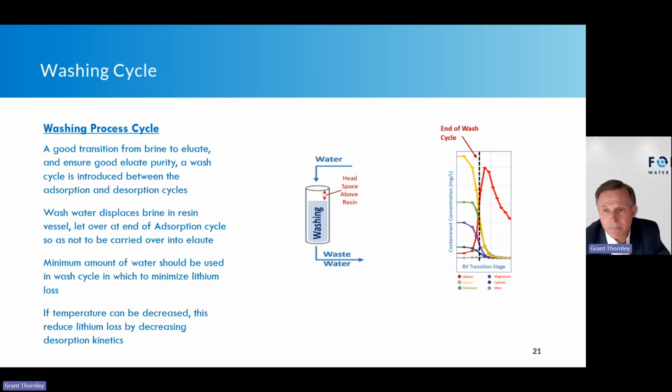And the way we do that is, again, a downflow process. And it's going to take out, here's that free space, or the head space above the resin. That's filled with brine. There's some brine down here. There's brine in between the resin particles. And I take water in a very laminar downflow, plug flow method. I push or squeeze the raw brine out of this.